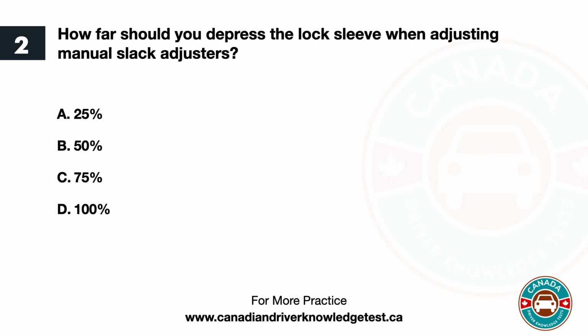Question 2. How far should you depress the lock sleeve when adjusting manual slack adjusters? A. 25%. B. 50%. C. 75%. D. 100%. The answer is D. 100%.